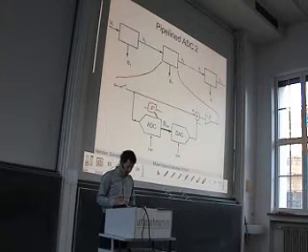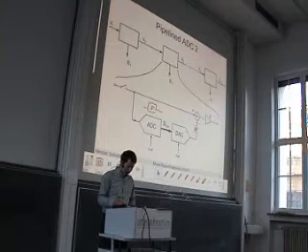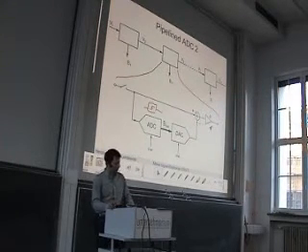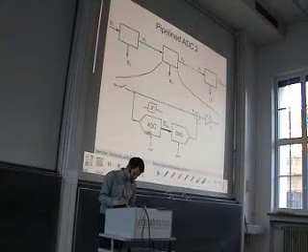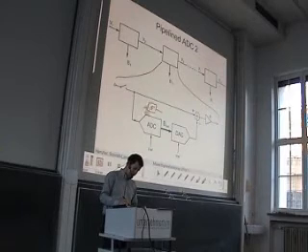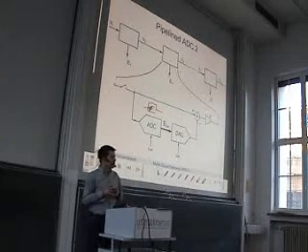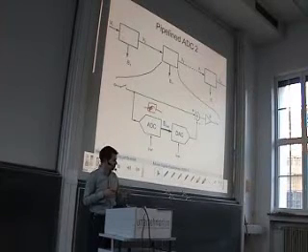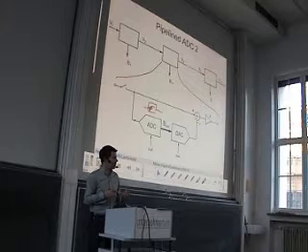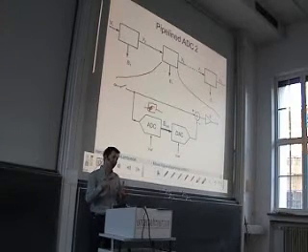The result of the quantizer is passed to the DAC. Then we subtract input signal and DAC signal and amplify it by a factor of 2. So why is here written ADC and not single bit quantizer? Well, because the concept is more general than we saw it from this basic algorithm. In this algorithm we said we process in each loop cycle 1 bit. We check is it larger or smaller than 0.